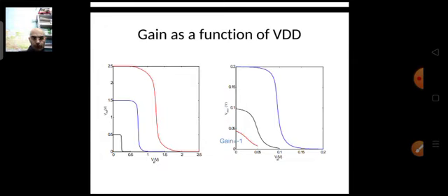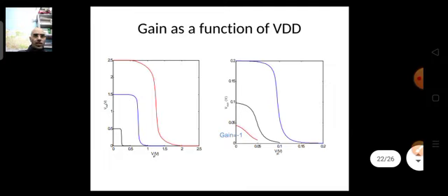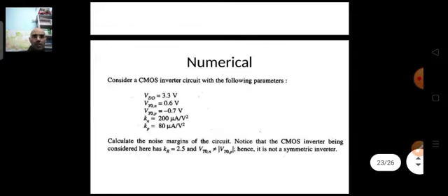But if we keep on further decreasing it and go into a smaller range, beyond let's say 0.5, which is the threshold voltage of an NMOS, then it will behave in a different way. It will have some hysteresis loop, but we are not going to see that in detail here. As far as our introductory course is concerned, we just want to see that if we keep on decreasing the VDD, our inverter still works as an inverter. With this we finish today's discussion, and this unit is over.